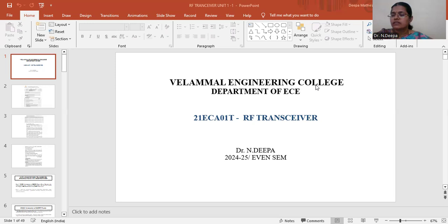So RF circuit design is involved with the top-down design and implementation process. We will see one by one in forthcoming chapters. An RF circuit is a special type of analog circuit operating at very high frequencies suitable for wireless transmission. One important feature of this RF circuit is the use of inductive elements to tune resonance circuit operation around specific radio carrier frequency.